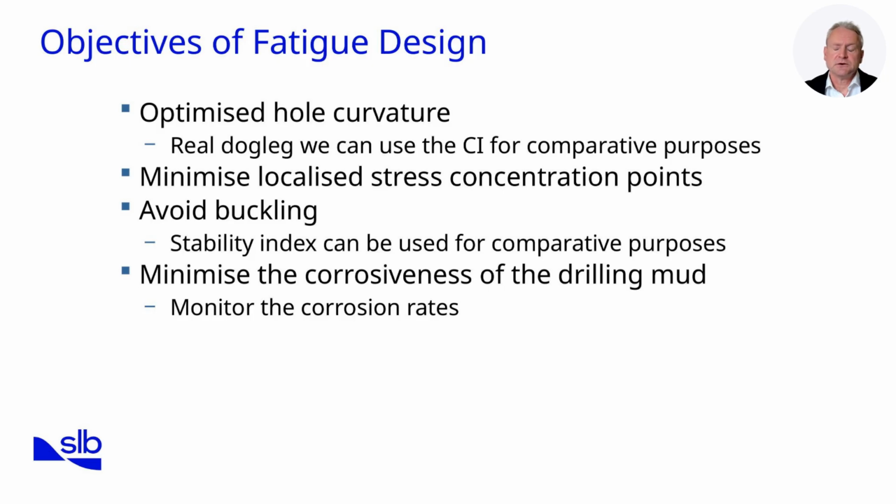Fatigue design also considers the chemical environment. Corrosive drilling muds accelerate crack growth, meaning it is essential to select proper fluid formulations and to monitor corrosion rates throughout operations. In practice, fatigue design means balancing mechanical, operational, and chemical factors to ensure the drill string remains structurally sound over the planned drilling program.